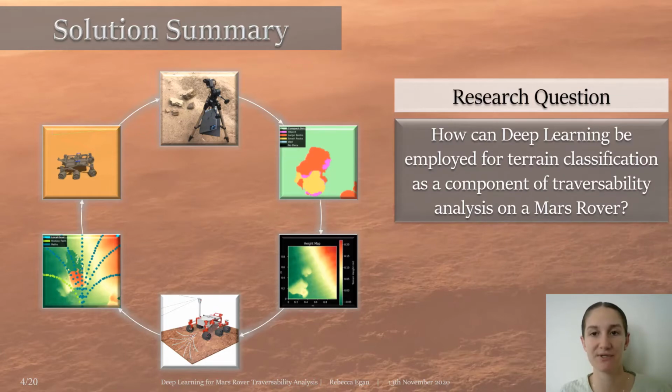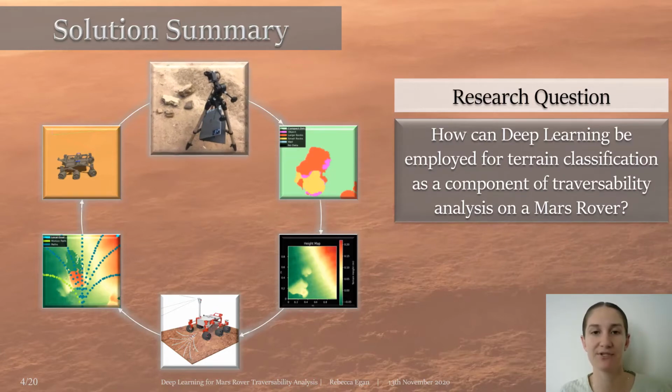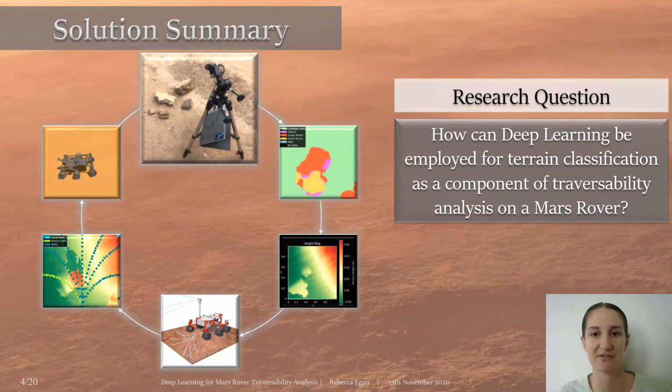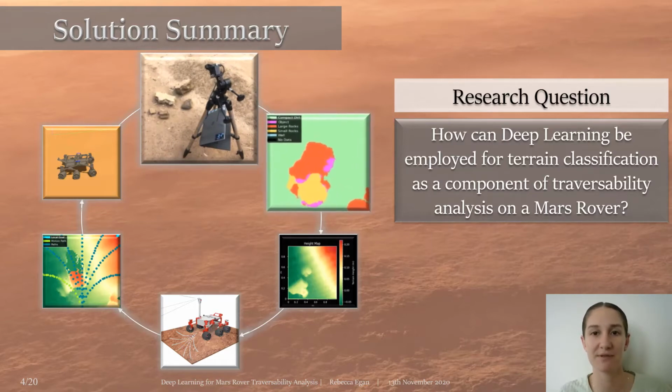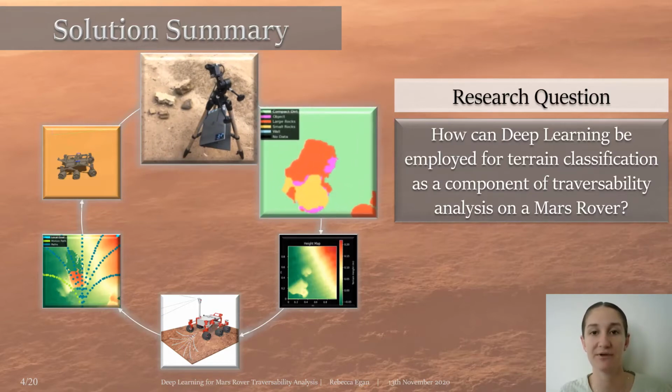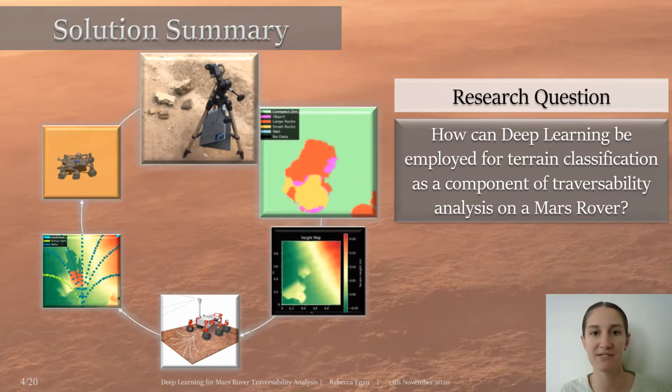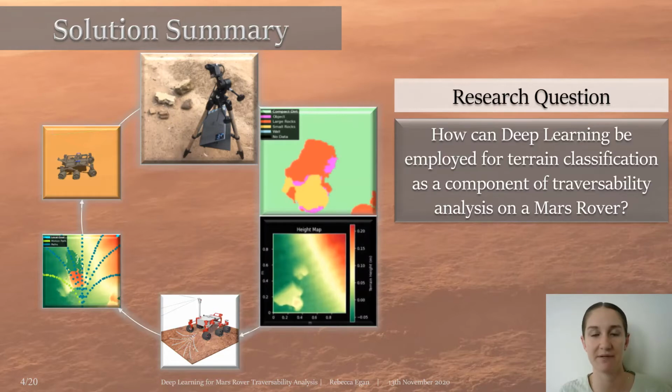The proposed solution consists of an RGBD camera, which obtains colour and depth images of the surrounding terrain. A trained CNN performs semantic segmentation on the colour image, yielding pixel-wise class labels identifying each type of terrain. A height map is constructed by the deprojection of the depth image.